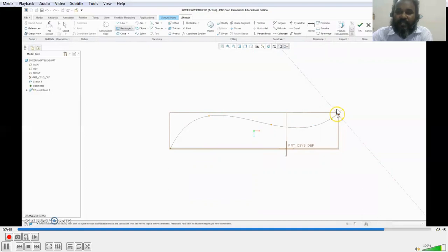All I have to do is create a feature here, which is a rectangle, and create a feature here, which is a circle. Once that is done, I just press the tick mark, and I get the swept blend option at the end of it. I hope I'm able to show you the final output. I'm going to play it again. Let us see if it pops out.